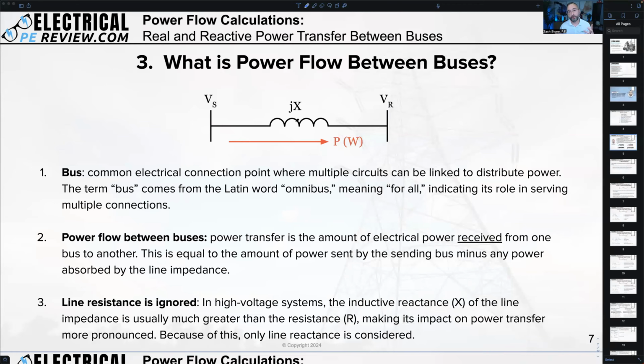Most of you are familiar with the term bus, but where did that terminology come from? Think of a really big, heavy-duty conductor, right? In the industry, especially if you've worked on motor control centers, you see the big rectangular copper bus bars, real thick, handle a lot of current, with holes punched through so you can lug connectors on them.